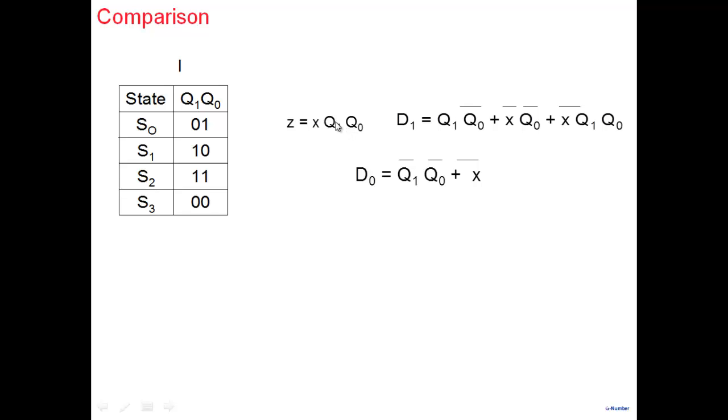In this particular case, we'll do a quick estimate. Each logical operation that you see here, so there is an AND operation between X and Q1, and there's another AND operation between Q1 and Q0. So each operation will count as a gate. In other words, this one that you see here, we'll implement in the form of two input gates. So Q1, Q0, one AND gate, and then the output here is ANDed with another AND gate here. So we'll say that the cost of implementation of this particular output logic is 2 gates.